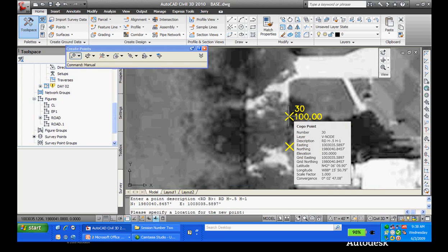Which way I'm going, yeah. So as the direction I'm walking, positive will always be to my right, negative would be left, and as we saw, if they mess that up or whatever, we can fix it pretty easy. All right, get to the driveway, just like we saw with the stripes. Well, at this point right here, that's an RD shot, and then, oh, by the way, that's going to be DW for driveway, or whatever my code is, space B for begin. Okay, now I'm going to send my guy up the driveway.